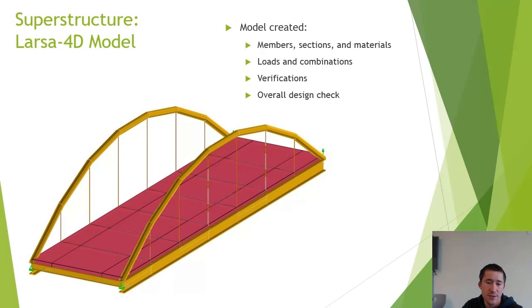The superstructure is primarily designed and checked through a LARSA 4D model that can check stresses and displacement. To verify the model's accuracy, its displacement and weight reactions were compared to calculated values. Note that AASHTO's LRFD bridge design specs were used for the model loads and load combinations.